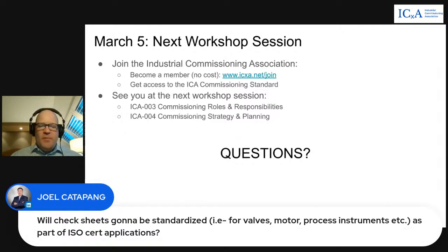Will check sheets be standardized for valves, motor, process instruments as part of ISO cert applications? So what your best approach with that is, if you get the right commissioning software, all of these standard check sheets are all pretty much preloaded in there. So you're right, how you test a valve, how you test a motor, the checklists that are required for these, it hasn't changed in decades, right? How you test some of the process instruments is the same today as it was largely 30 years ago, right? Unless there's been some real technological advancements there.